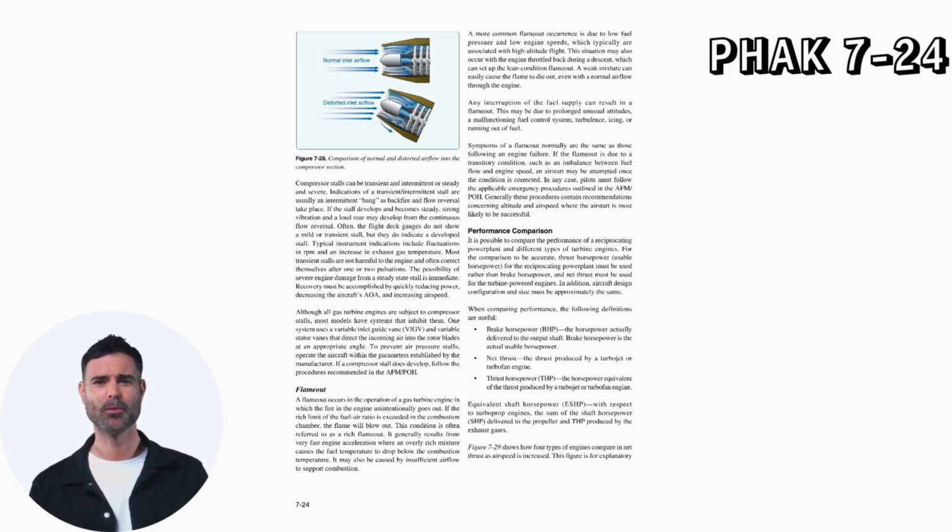Symptoms of a flameout normally are the same as those following an engine failure. If the flameout is due to a transitory condition, such as an imbalance between fuel flow and engine speed, an air start may be attempted once the condition is corrected. In any case, pilots must follow the applicable emergency procedures outlined in the AFM-POH. Generally, these procedures contain recommendations concerning altitude and airspeed, where the air start is most likely to be successful.